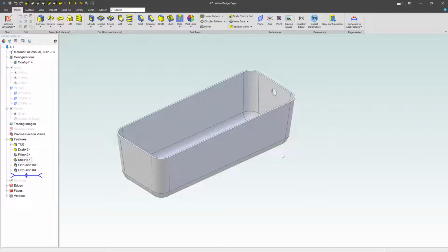So if you're going to be molding a part, or thermoforming a part, it might have a shrink factor to the plastic. And maybe that shrink factor is like 2%, right? It's a very small amount. But what I have to do is build this part a little bit bigger first. So I have to scale it up a couple percent, so that when the final part is built, it's going to be back to the original size. So that's how you might use scale.